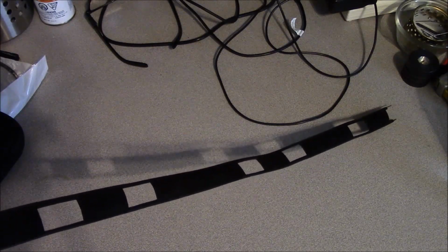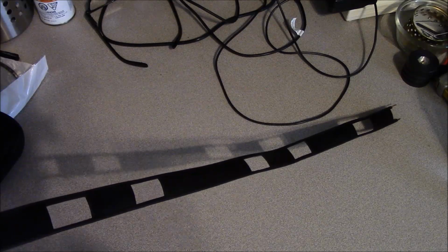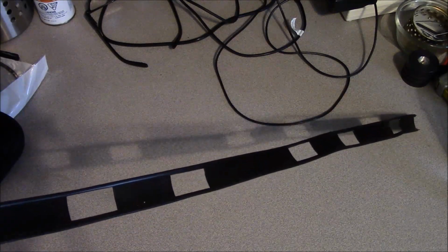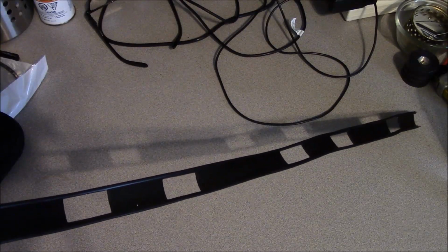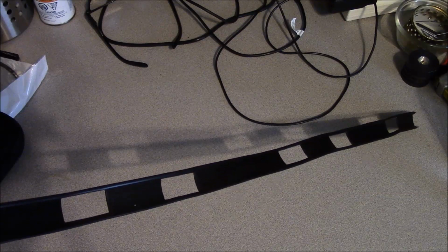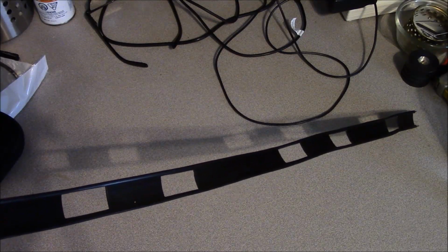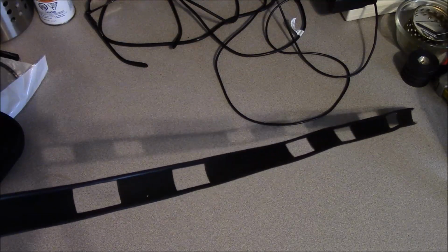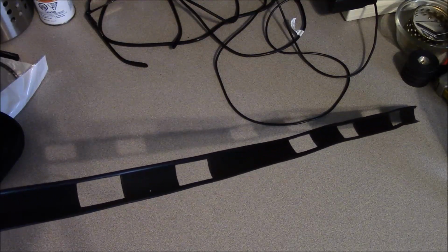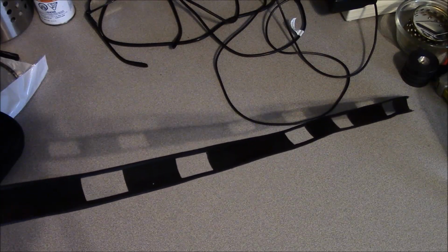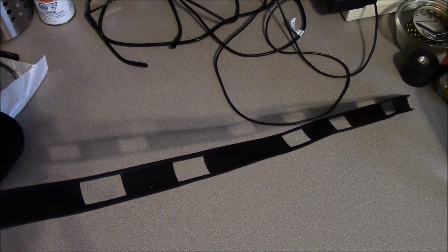300 ohm twin lead, which is like what we used to use in television sets before cable television, and those of you who remember life before cable television will certainly know what I'm talking about. That right there in some home improvement stores is still available, and that right there you can make feed line out of that if you can get your hands on it. But typically television coax is going to be far more likely to be an available resource to you than finding 450 ohm balanced feed line.